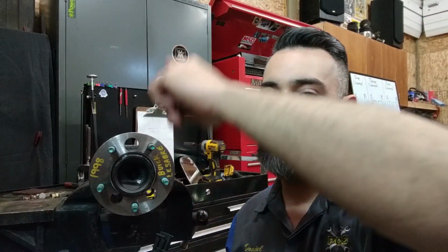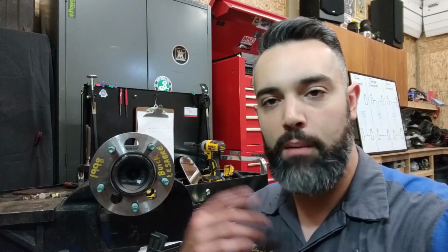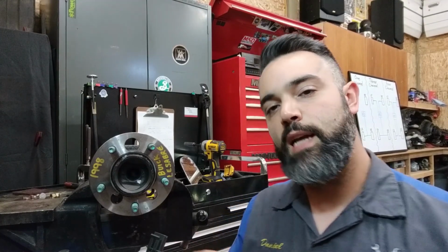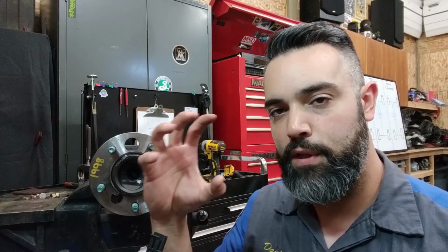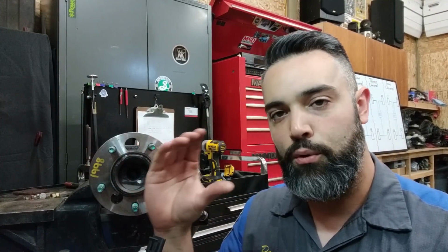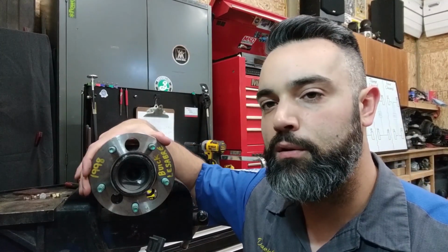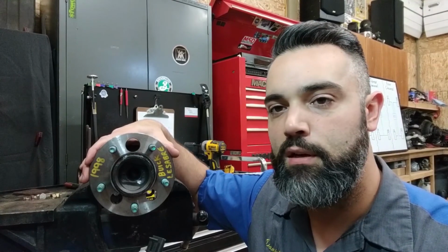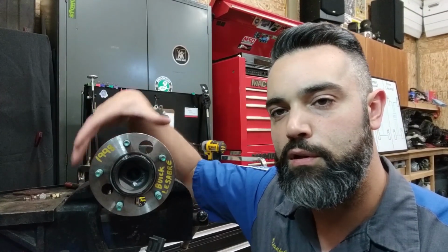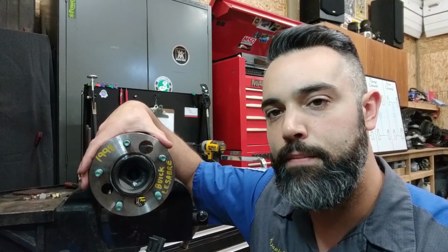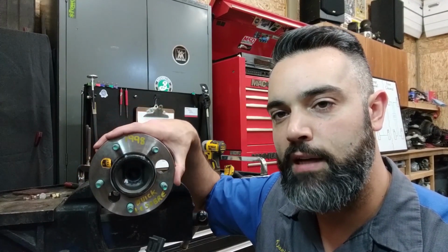It's going to reduce the pressure, so it's going to route that brake pressure back in through the accumulator, and this is going to pump fluid. Then it takes that stored energy of the fluid that's being recirculated through and stored in the accumulator, and it routes it back to the brakes and lets it reapply the brakes. To allow this in one cycle from a lockup or slip condition, it's isolated at a lockup, then it reduces pressure, then it reapplies.